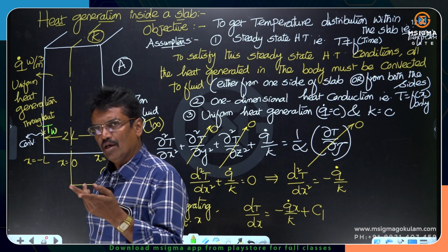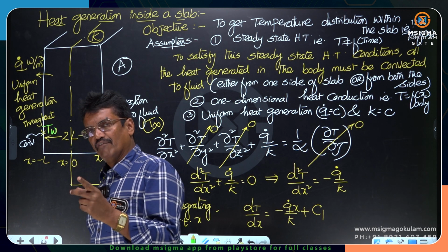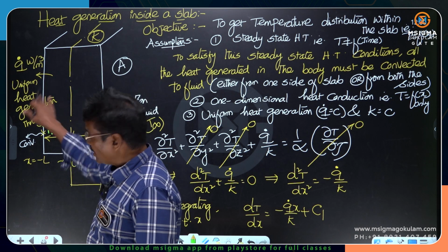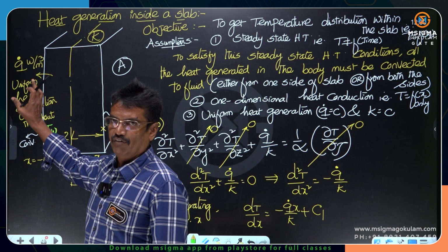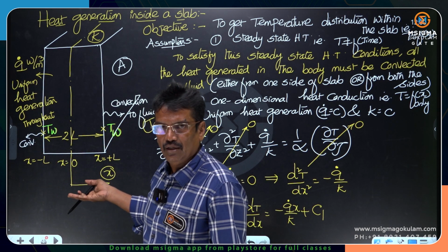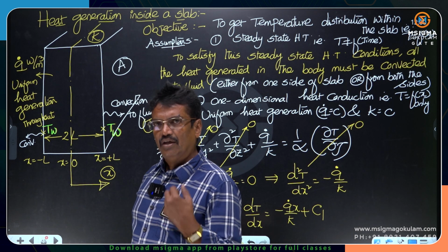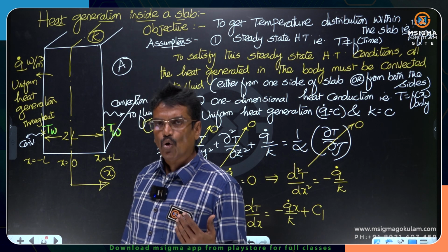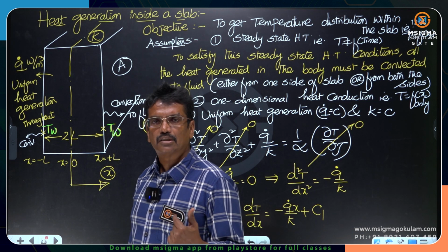Therefore, the temperatures will be relatively low on that side where there is forced convection or wind. The other side is natural convection, still air. It is also taking heat, but slowly. The rate of convection heat transfer is lesser, therefore the temperatures may be higher.